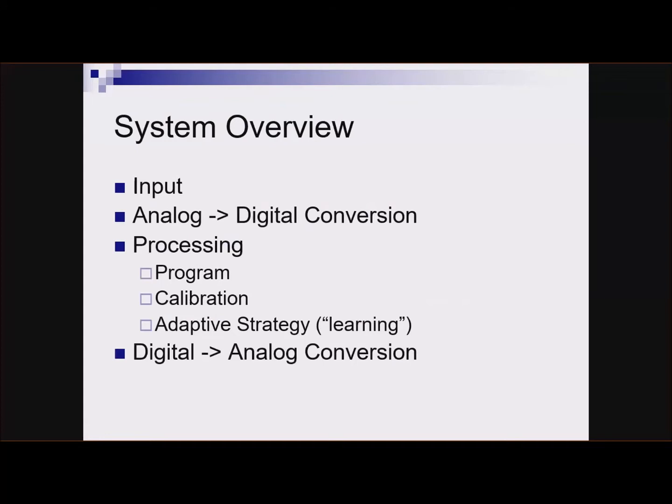Then on the output side, sometimes outputs are analog. Well, not super often, but think about fan speed. That's a good example. We have an HVAC system. It has a blower motor. If that's electronically controlled, the computer is a digital device. The fan is kind of an analog device where more current flowing through it makes it spin faster.